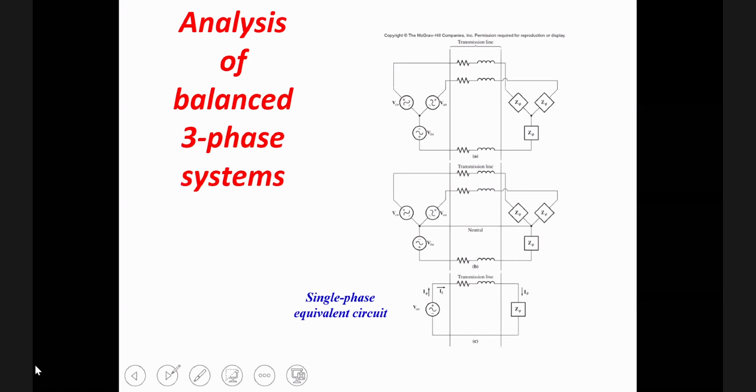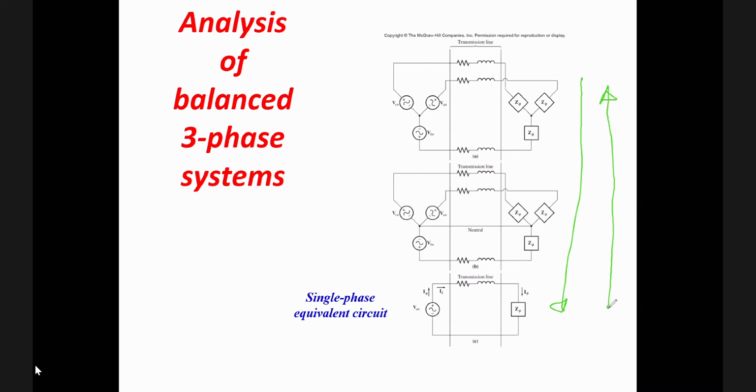This is just an explanation here of what we should do if we have transmission line impedance. And I already explained this many times. We need to go to the single phase representation. We analyze this, and after that, we go to the original system again. This is the only way. So this is the single phase representation of such a system.